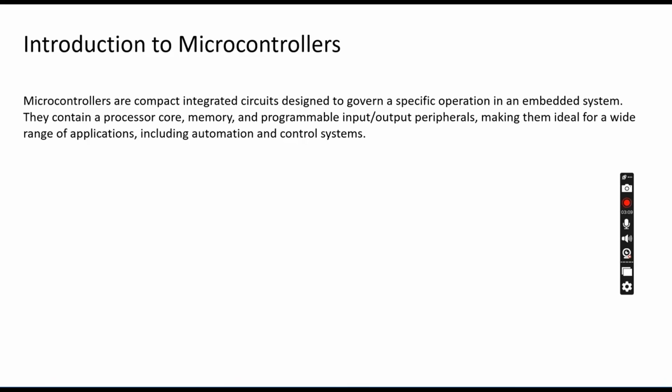In this implementation of the washing machine, we are using the microcontroller PIC 16F877A. The PIC 16F877A is an 8-bit microcontroller from Microchip Technology. It has 8K flash program memory, 368 bytes RAM, and 256 bytes of EEPROM. It also has 33 input-output pins, a 10-bit ADC, timers, UART, and more. This is ideal for embedded applications like washing machine control.